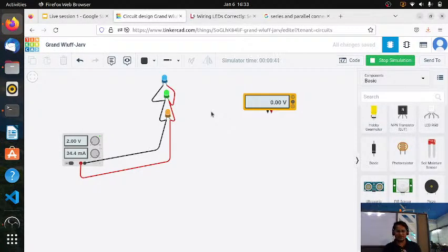If you observe carefully, in the series connection we had applied 6 volt to glow 3 LEDs, because if you apply less volt, like 5 volt or 4.5 volt, the 3 LEDs were not glowing. But here in parallel connection you just need to apply 2 volt, because an LED actually needs 2 volt to glow, and multiple LEDs you can connect in parallel, all will glow.